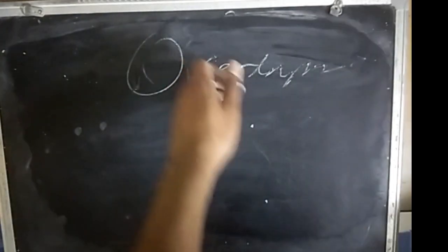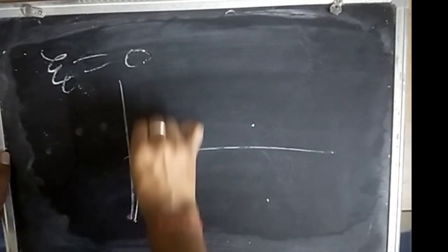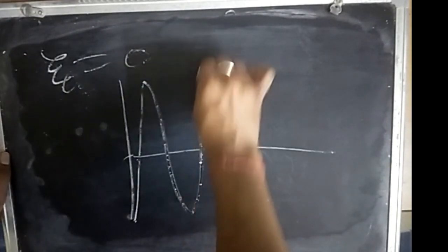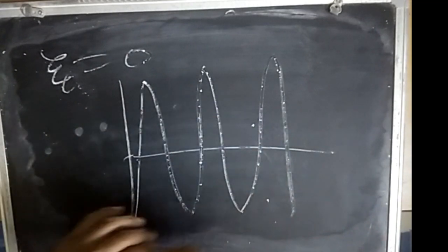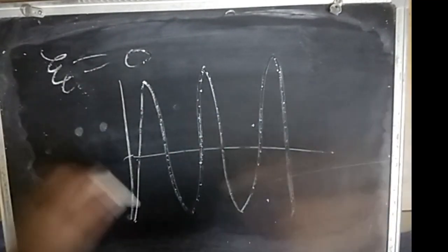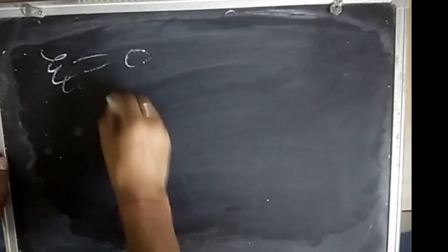Okay, so these are overdamped, so they are slow actually, these both tanks and systems. Now the main thing here is what will happen if zeta is 0. When zeta is 0, this peak will be attained, and then it will again attain the same peak. So the decay ratio here would be 1. Why? Because there is no decay actually. Let me see. So decay ratio, that is R by Q, these both are the same, so it will become 1